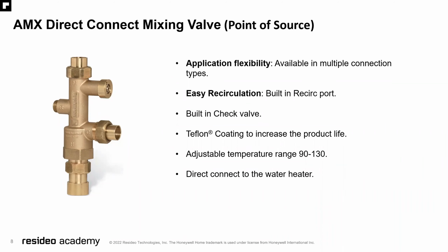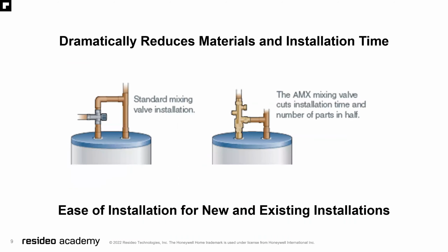And when I say direct connect, it literally drops right in on top of the water heater. You can see here with a standard mixing valve, you have to do a T for the cold water side. And some plumbers prefer just to drop in the mixing valve and T over directly into it.